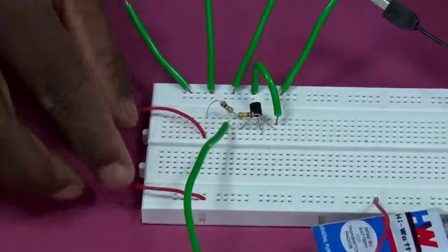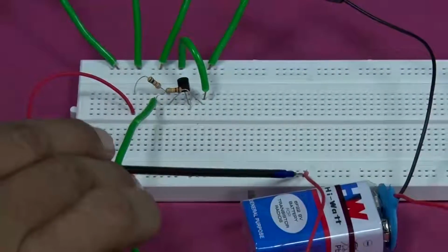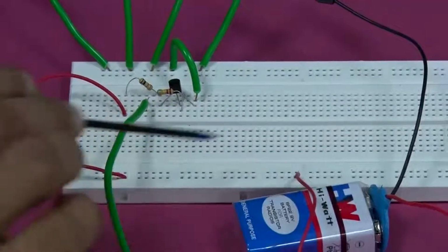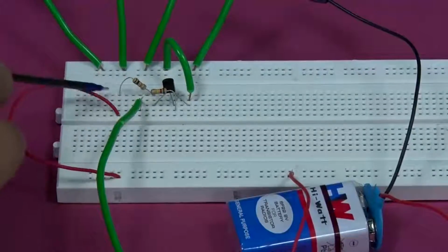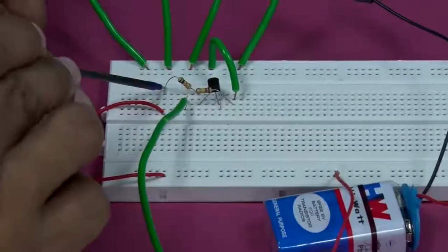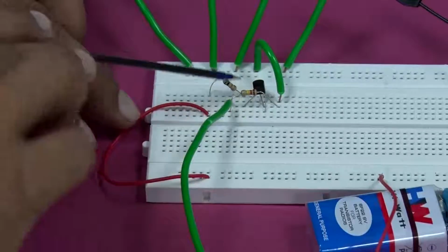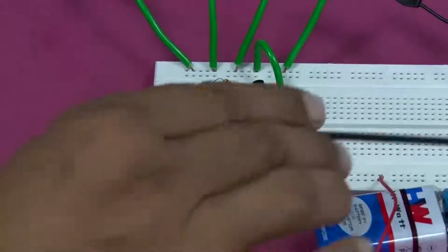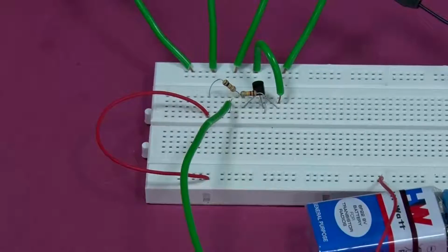very good. So, you understand the working of the breadboard. This positive of the battery is joined here, but these are all internally connected. So, that 9 volt which is here is also coming here, and from here I am going to this point, and then these ones are internally connected. So, this 9 volt has been connected to this other end of the resistance. One end of the resistor is already connected to the collector. That part is done. The negative of the battery is already at ground. So, our output side is also complete.